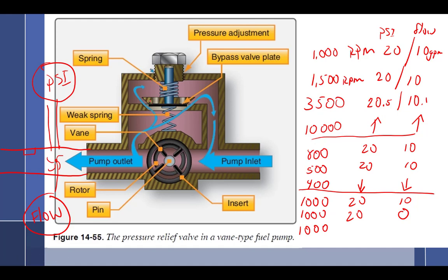Given and depending on how high this was, what is the pressure likely to do at this point with a much wider orifice? Decrease. Probably drop a lot. So the pressure is going to go way down. Why? Because there's nothing blocking this here. It's free flowing through there. All right? And what's the flow going to do? Increase. It's going to go up. Why? Because there's nothing blocking it. So yes, the pressure goes down, the flow goes up.